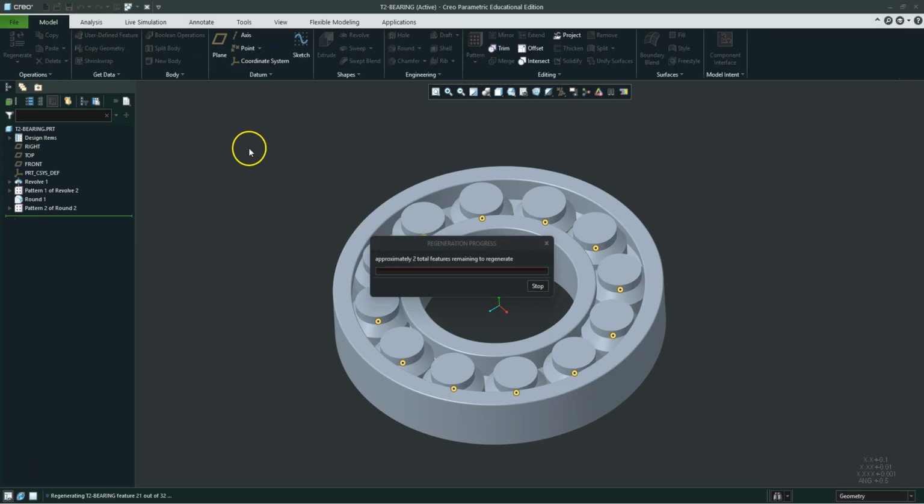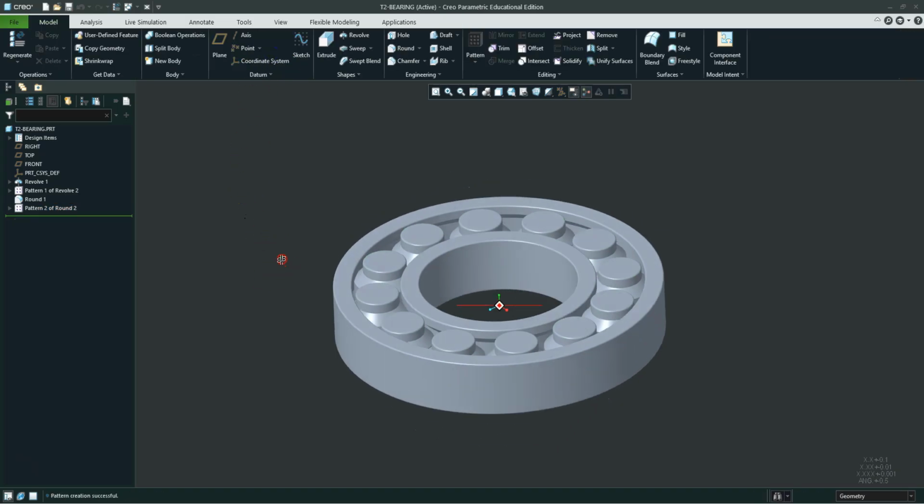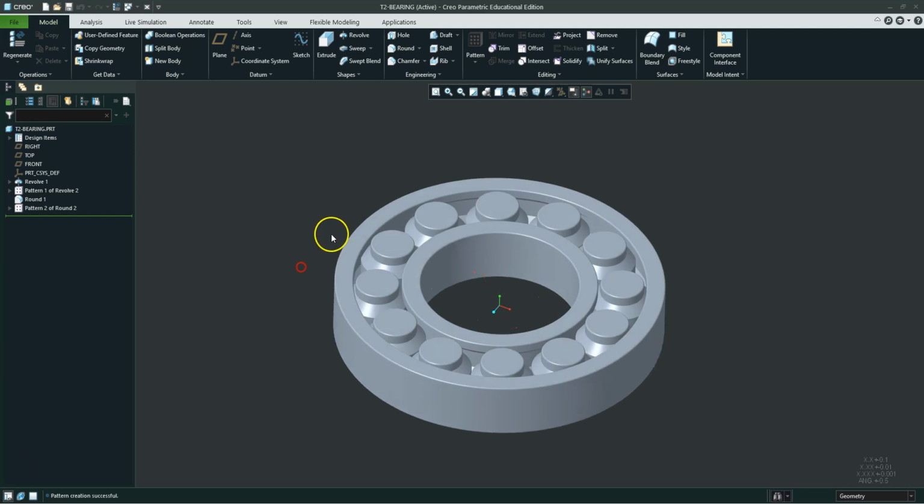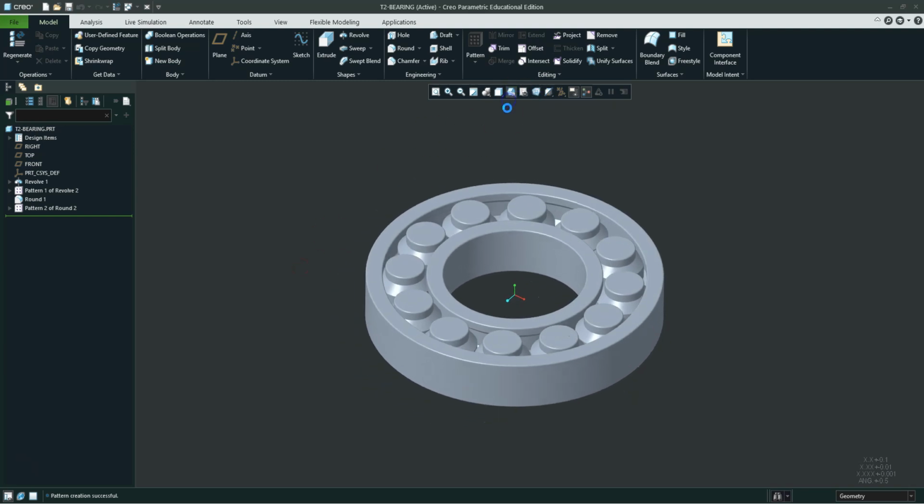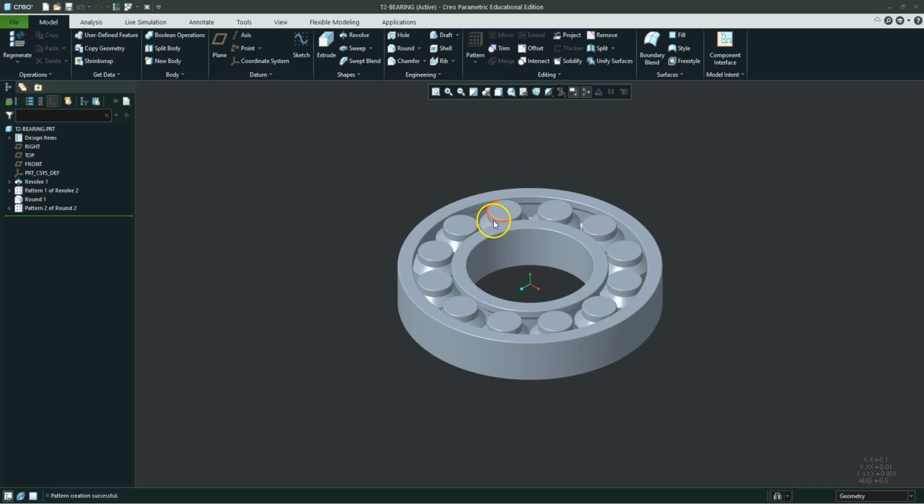So I'm going to hit my checkbox. And now I automatically have all those rounds around there. Reference patterns save you a ton of time. If you think about putting in washers and bolts and nuts and things like that, if you make a hole pattern, you can reference pattern all those things that relate to that pattern all at once in a couple clicks, rather than having to manually assemble over and over again.